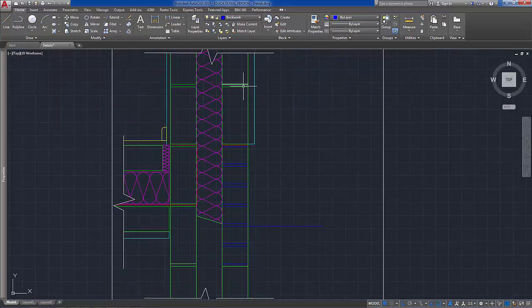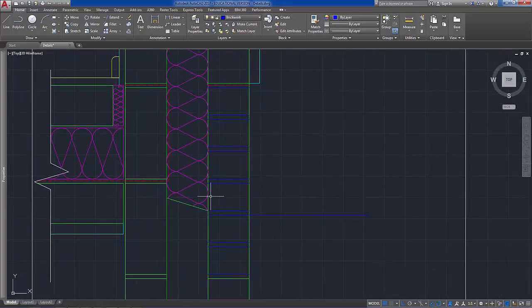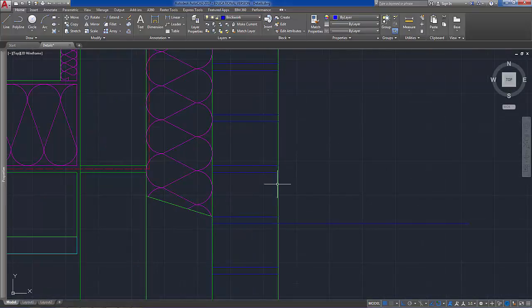The mortar joints, for example, are porous, and when rain is heavy enough it will get through there. And even further up where there's render, when it's wet enough, water may well seep in through, and so we need to allow for that to run down the inside of that outside leaf, and then have a means of escape or a way for the water to drain out. So that's what a weep hole will allow.